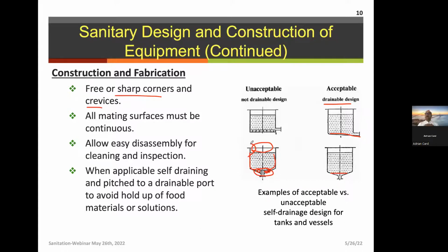When I was in the industry, unfortunately, this was the type of drain that was in our facility. We had a listeria problem that in some instances was associated with the poor drain design that we had in that facility. Had we had something like this, in which there are no areas for accumulation, this biofilm should not have formed.